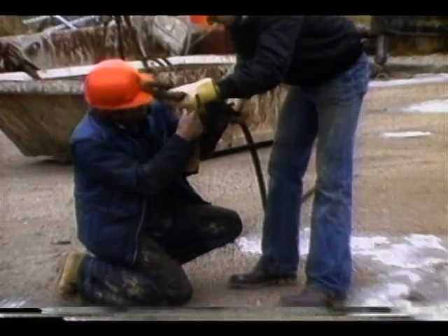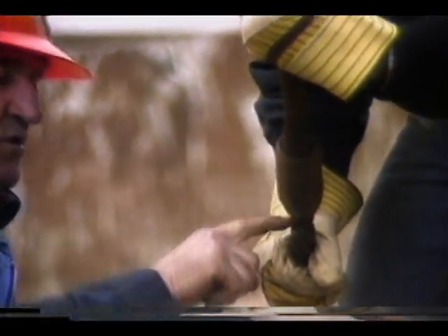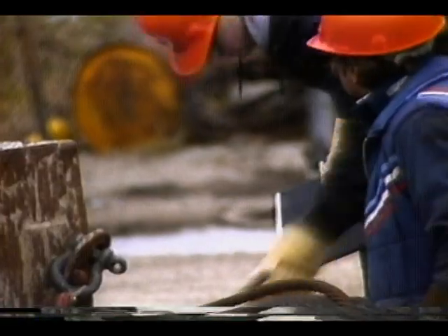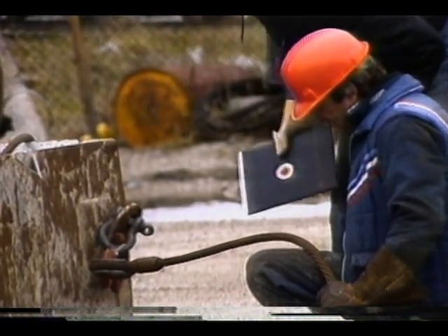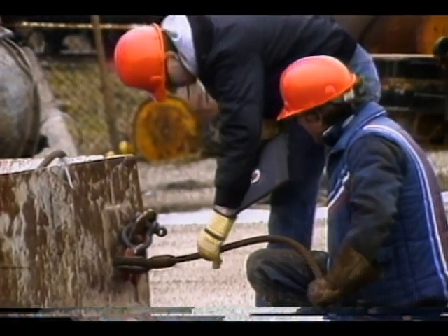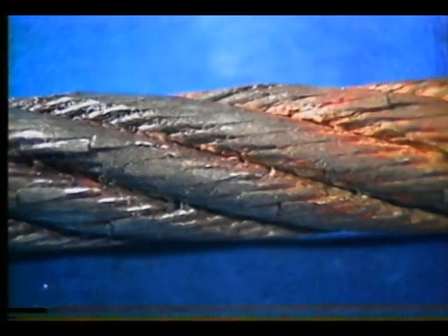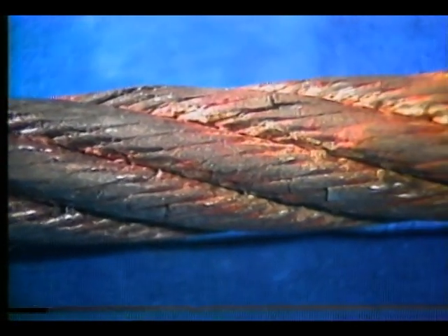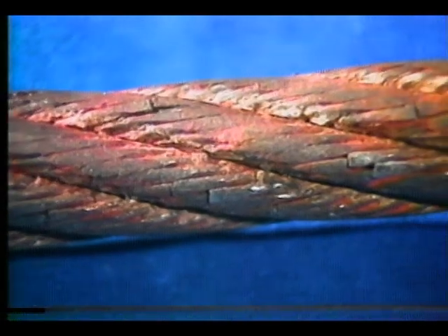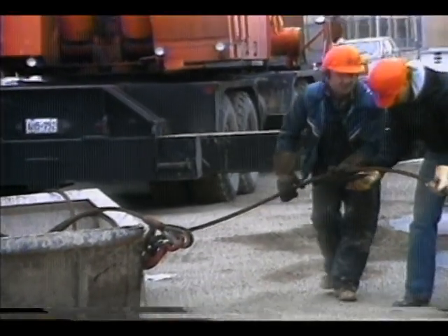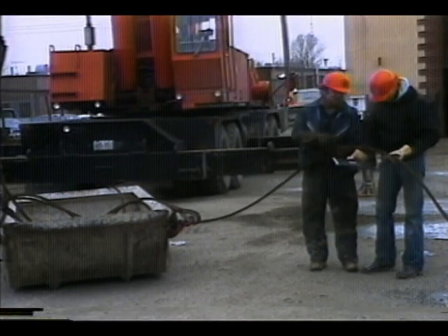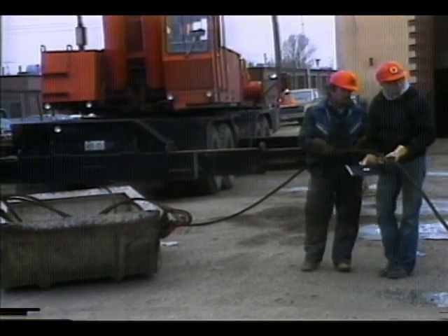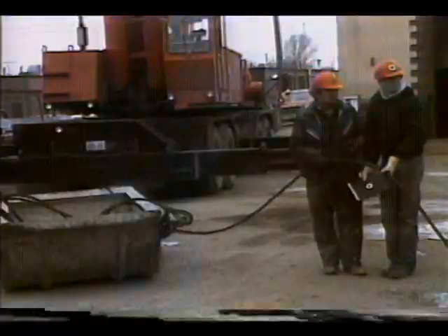The single most important operational check to be made on hoisting and rigging equipment is the rope and rigging inspection. Safety and economy dictate the need for periodic inspections of all load-supporting wire rope and fittings. Factors such as insufficient lubrication, abrasion, wear, fatigue, corrosion, improper reeving, and kinking are often more significant in determining the usable life of wire rope than strength factors based on new rope conditions.